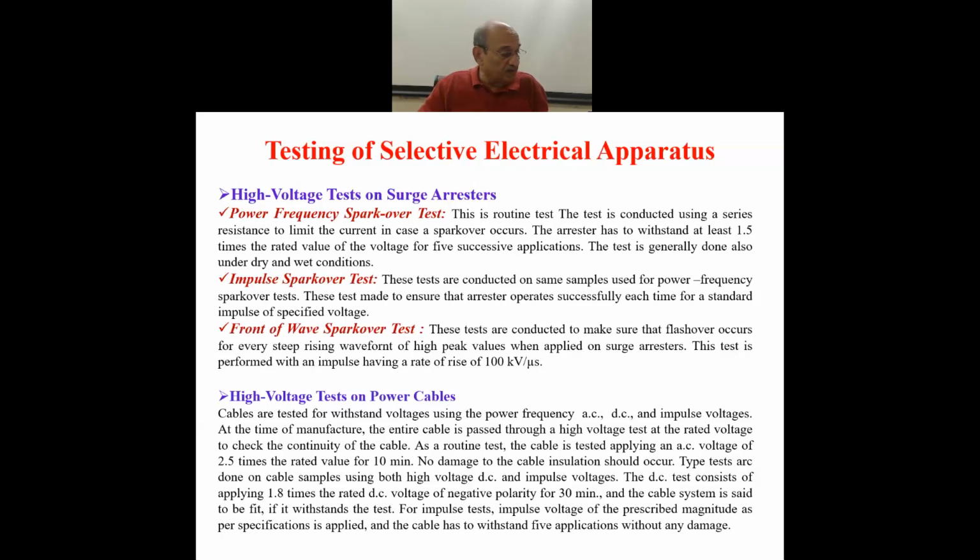When we come to the high voltage test in power cables, I mentioned that in power cables, not only at the finished stage but also in the intermediate stage, high voltage tests are performed to ensure the insulation quality.